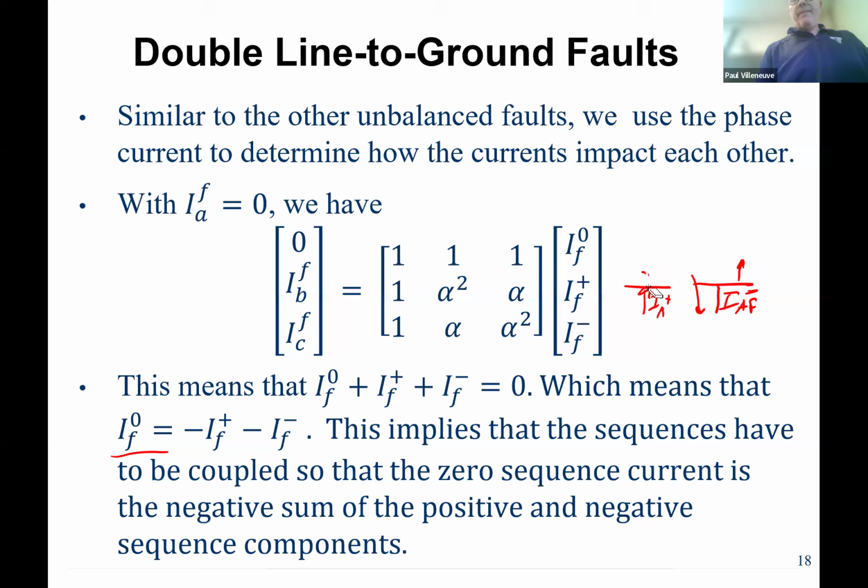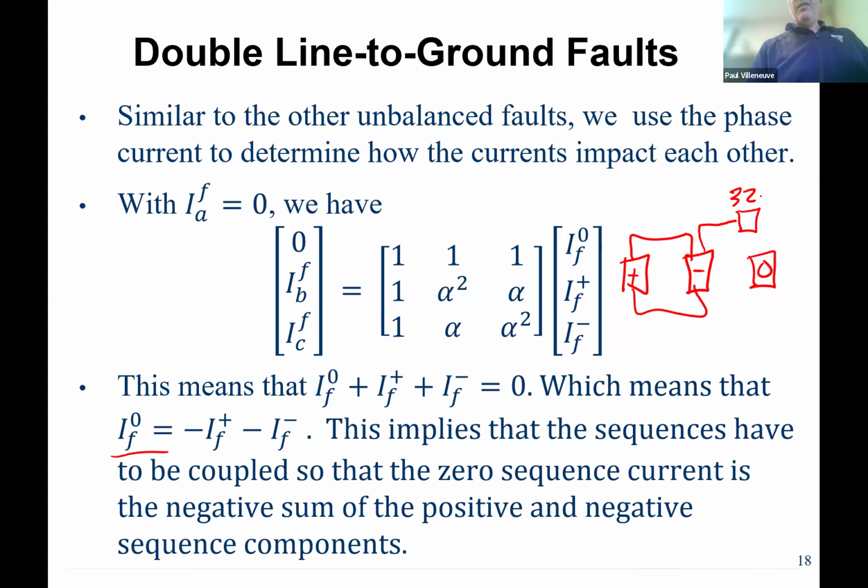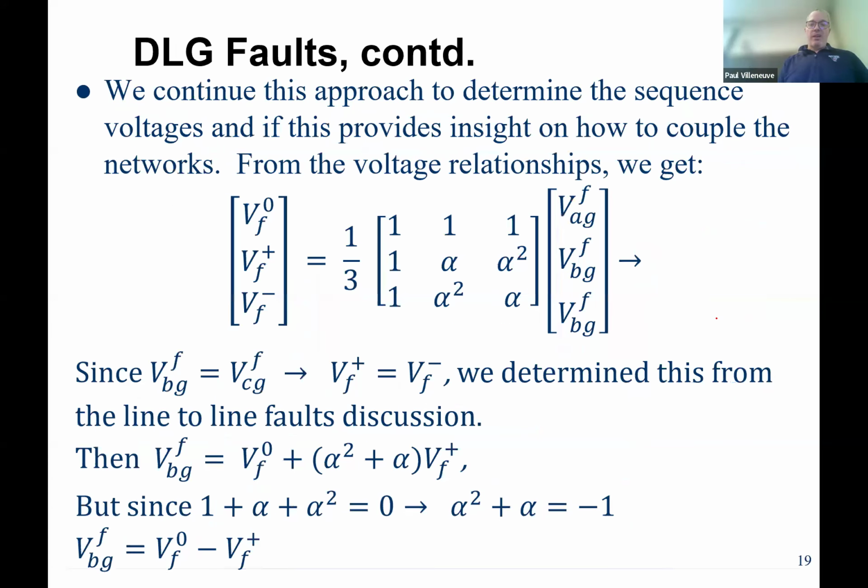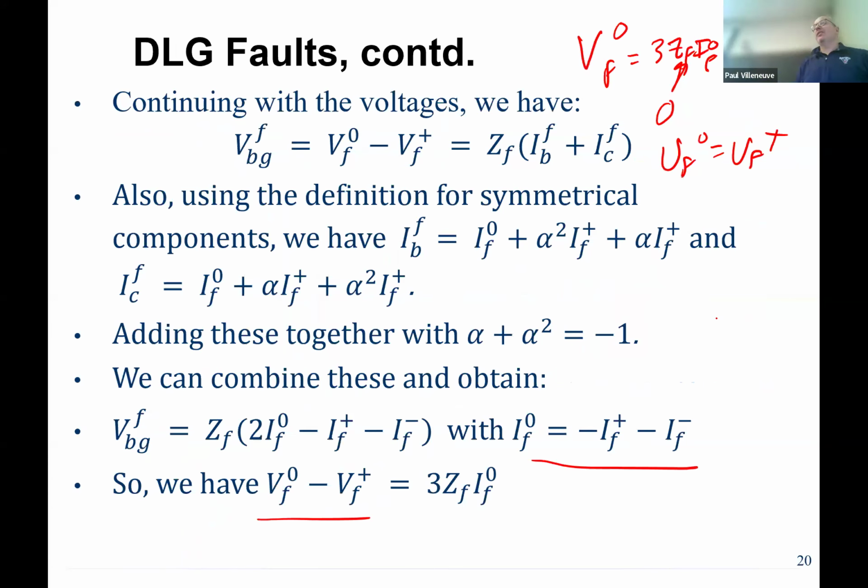clean this up. So here's our positive sequence diagram. Here's our negative sequence diagram. Here's our zero sequence diagram. These two go in parallel. This over here has to include our fault impedance, if it's not 0. If ZF is equal to 0, then they're all in parallel. If it's not equal to 0, we need to include that voltage drop there. That's what this last step tells us.